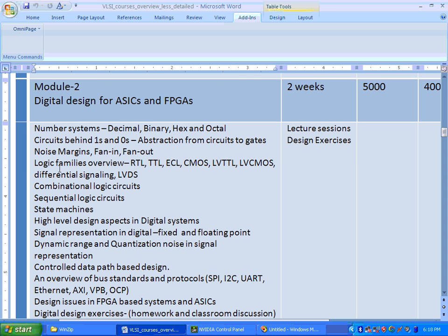Okay. Now sequential logic circuits. This is a more important topic for us. We would learn about what are called state equations, like how your combinational logic circuits will have y equal to a b bar, your sequential logic circuits will have Qn+1 as a function of Qn. Qn happens to be the nth clock cycle output of a D flip-flop. Qn+1 happens to be the n+1 one.